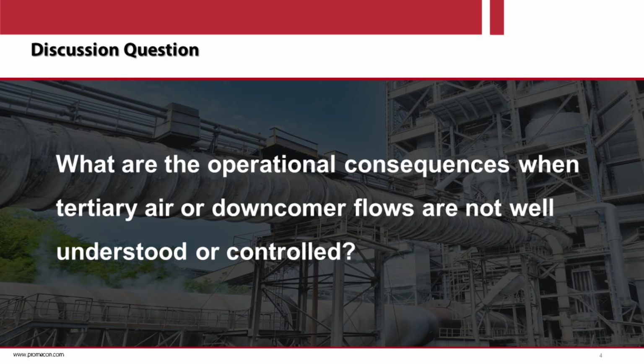And that will be instant. And that will be a much more reliable measurement than just relying on pressure of the draft to know that a buildup is coming. You could even monitor the buildup at the kiln inlet. And of course, the other thing is that this is typically associated with poor combustion, of course, in the calciner. So that's it, exactly.